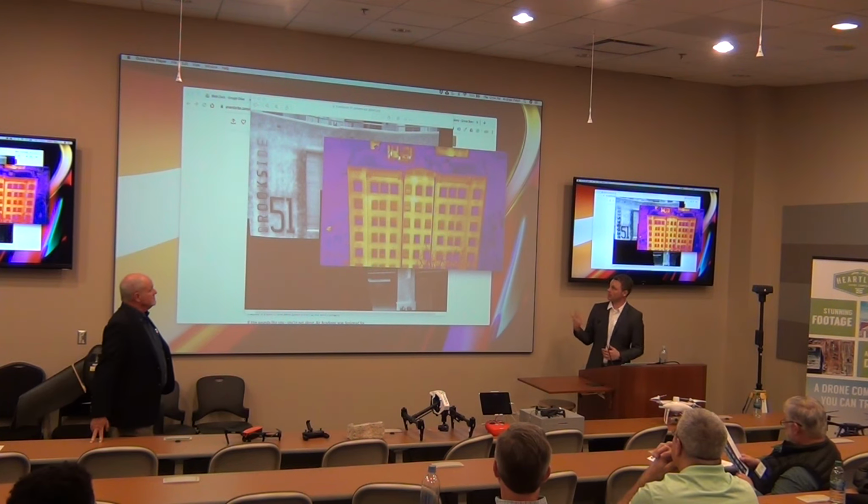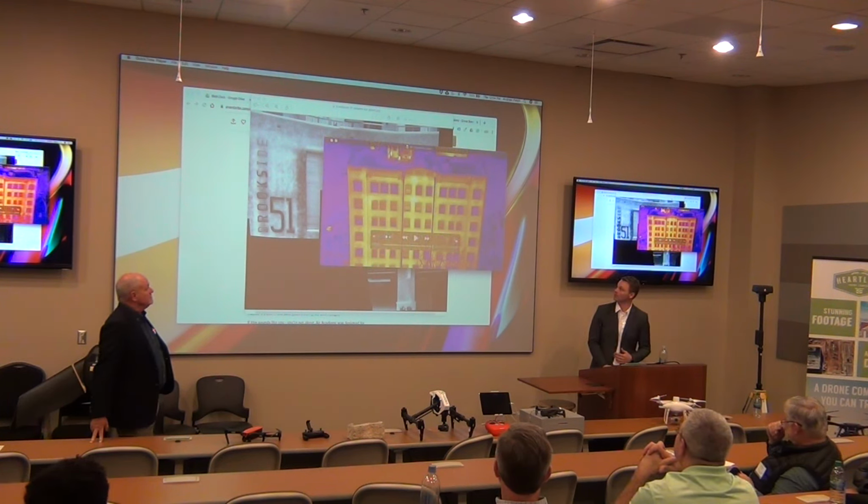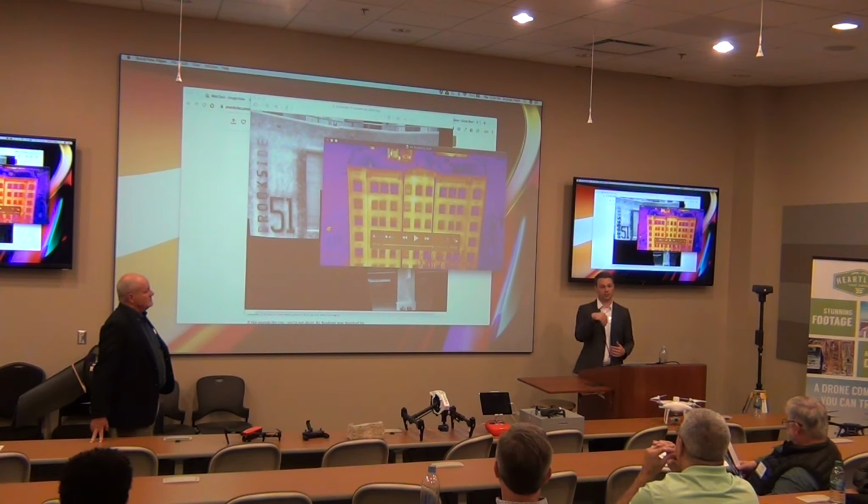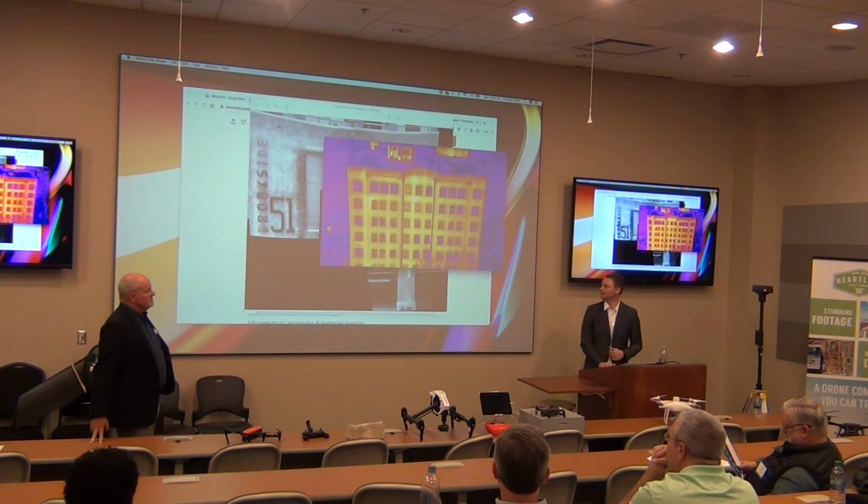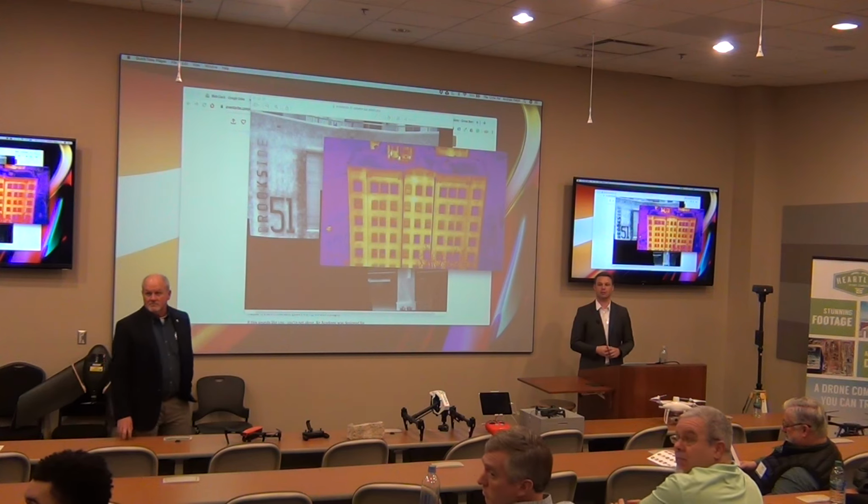Well, after we did our inspection with thermal and looked at the roof, we saw that there was water penetration going on in this section up here. Water was getting through the roof, hitting a ceiling joist, right, or pipe or something in the substrate, and it was running laterally and then getting into the wall and causing water spots on the wall. Well, and you can look, relatively new roof too.